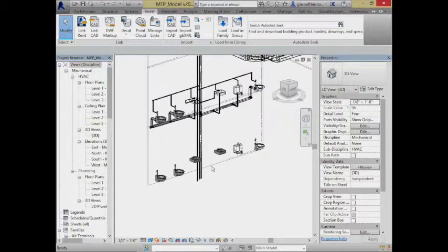The other thing you might notice about it is this issue of the slope. For the slope, does anyone know what the rules are about sloping residential pipes, or sloping sanitary pipes? How much slope would you guess it has to have? Does anyone know? 2%. I think it may be 2%. I think of it in terms of a ratio per foot. I always think of it as being 1/4 inch per foot. I've heard this morning that it could actually be as low as 1/8 of an inch per foot, but 1/4 of an inch is a little more slope. That's more of a recommended slope as opposed to a minimum.